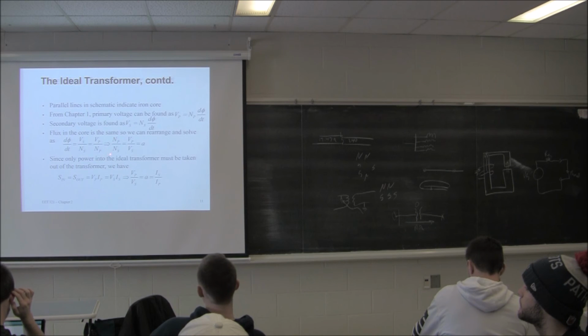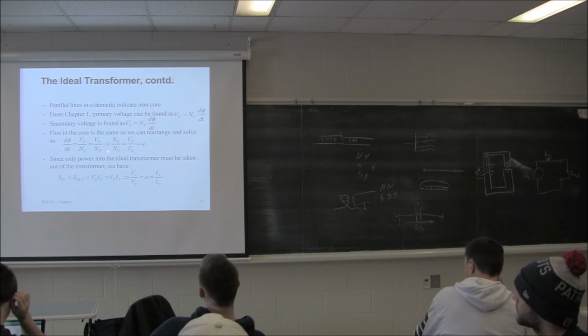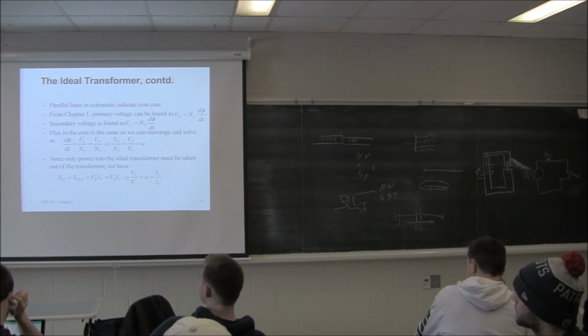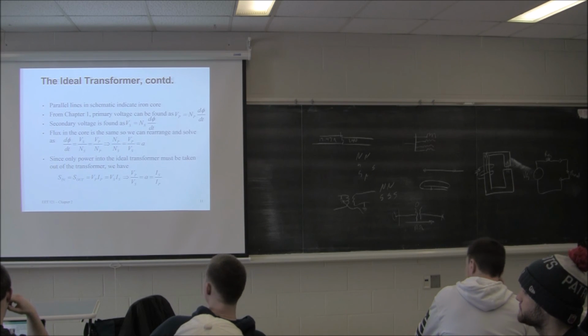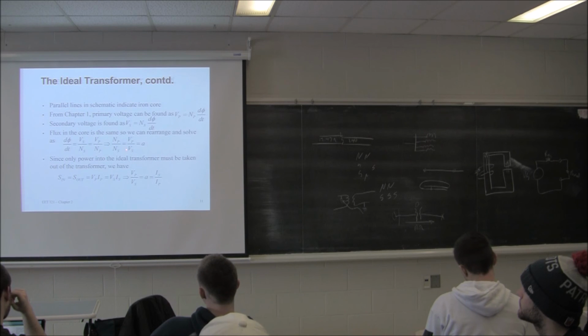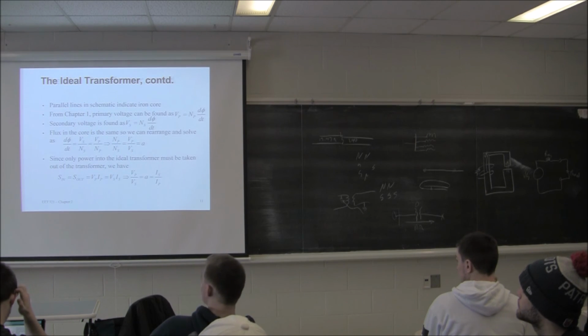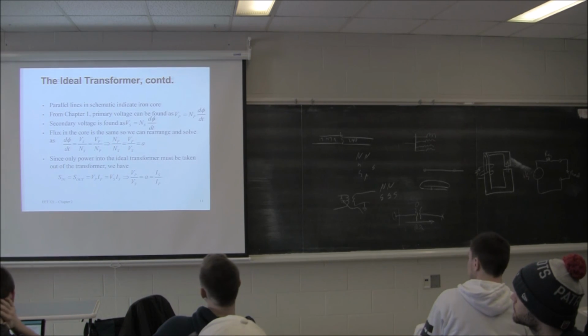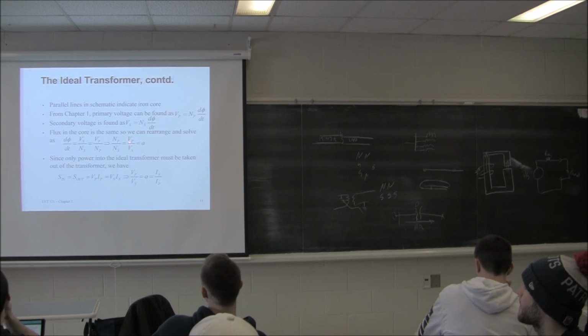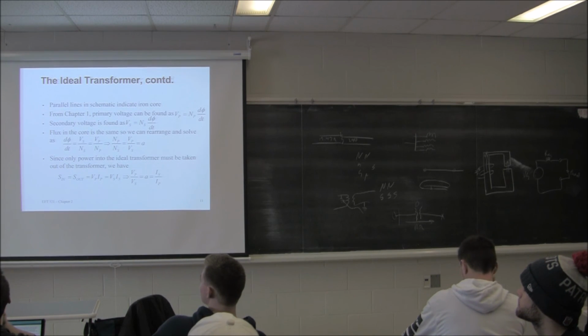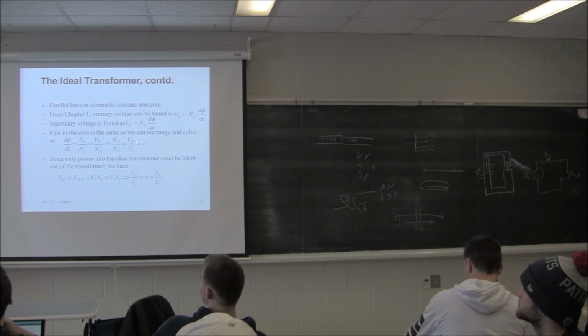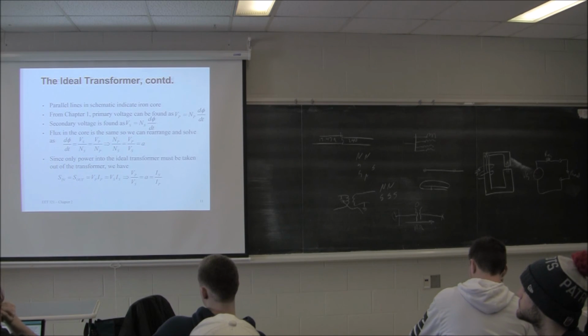Okay? So if you actually buy a transformer, you'll get the turns ratio, because you don't care what the turns are on the transformer. What you care about is it's a 4160 to 115 kV. That tells you the turns ratio. I don't need to know what the number of turns are. That's not relevant. So you never buy a 30 to 300 turn transformer. You buy a 4160 to 115 kV transformer. And that is analogous to the same turns.